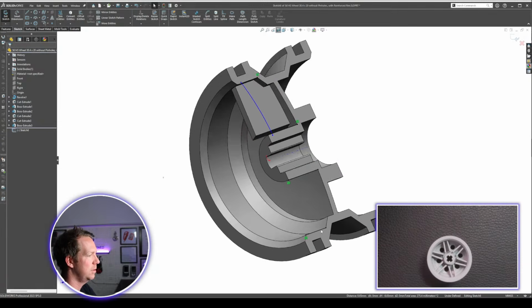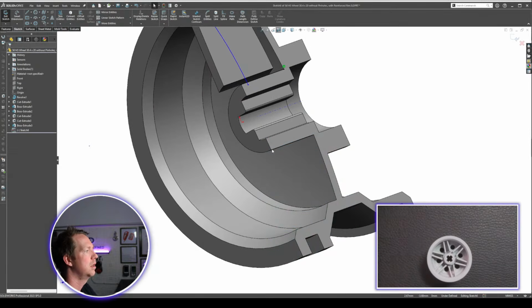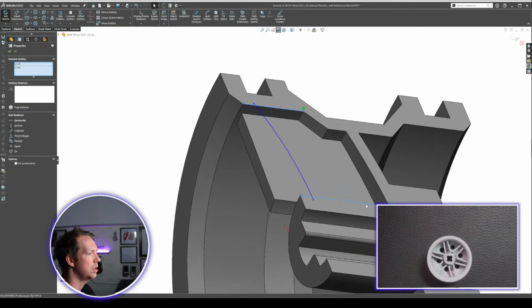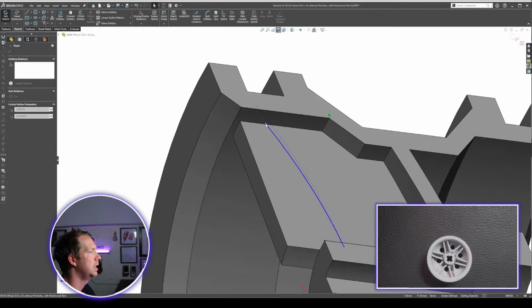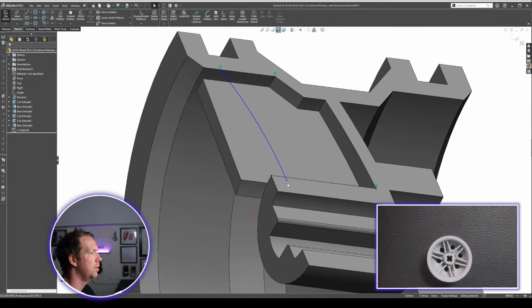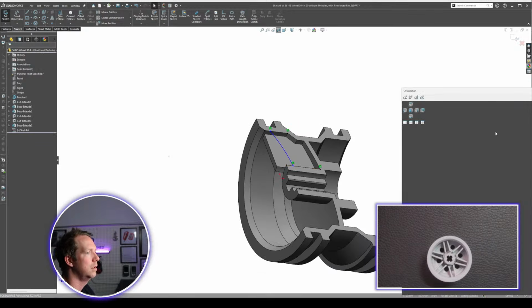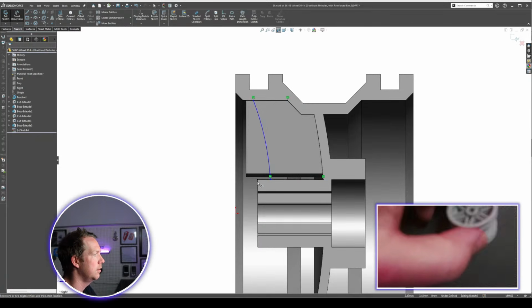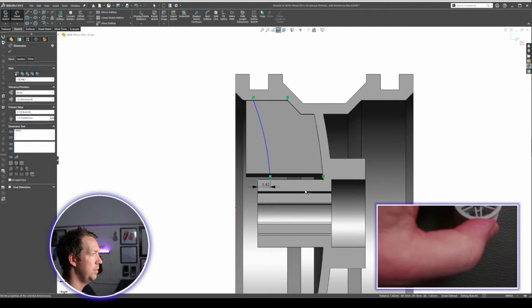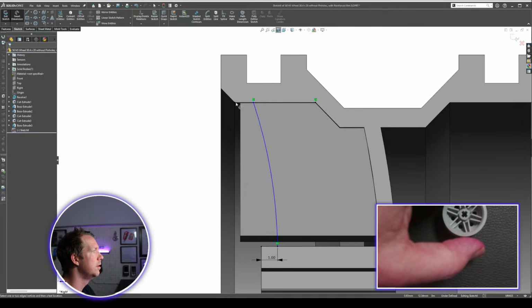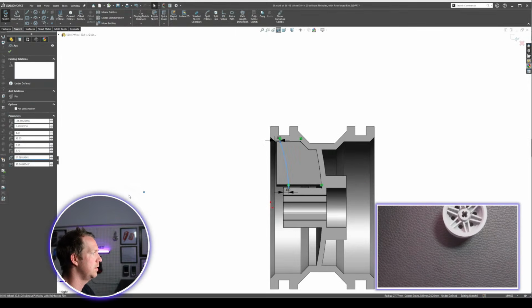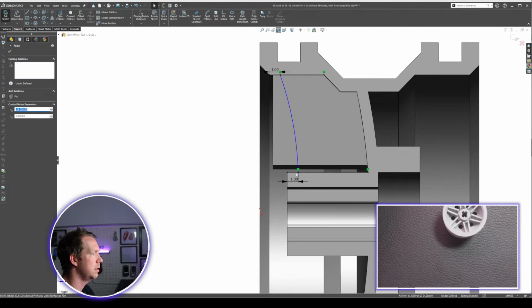It's going to create that line for me. It creates 4. Got some on these other ends too. I'm going to delete those. But what that gives me is geometry, which I changed to construction, gives me something to drop that and make it coincident. All right, that's going to help me fully define this. Because now I can say, okay, from here to here, it's 1 millimeter. And from here to here, that's also 1 millimeter, for instance. Finish it off and make this line.